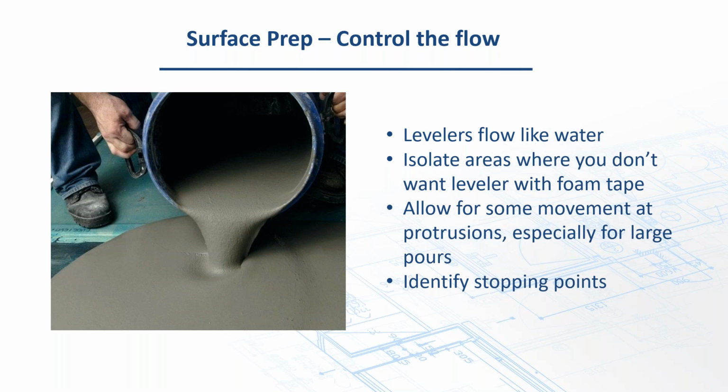And try to identify where you want to start pouring and where to stop pouring, so you can identify the day's work. You don't want to go right in the middle of the next day's work or anything like that. If you can cut it off in the doorway, that's ideal. If you can cut it off within a certain area, that's ideal. So identify where you want to get within that day's work. Maybe sometimes you put the primer down for the next day if you got done a little bit early.